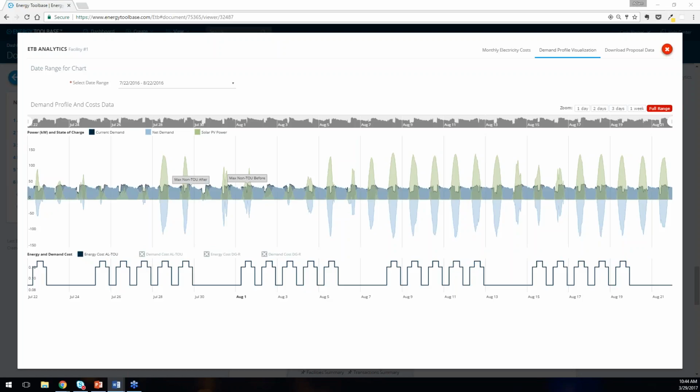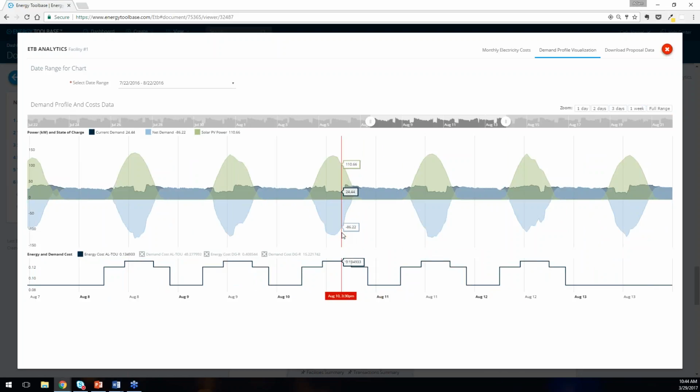I think a lot of times users of Energy Toolbase previously used PVWatts just because it's quick, not necessarily because it's accurate or very rigorous. You can build a PVWatts simulation in 15 seconds and it's good enough, within 10%, let's say. But now we're thinking about quantifying the effect of time of use rate changes, net metering version 2.0 scenarios and counting exports, or simulating the reduction of demand charges on commercial schedules, which is very, very important.